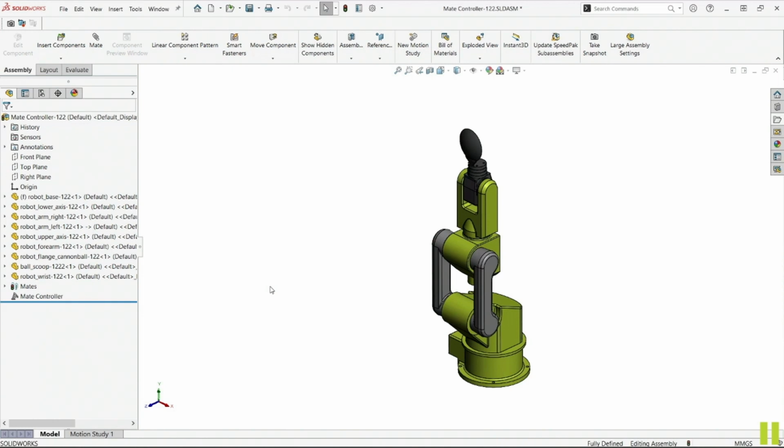Maybe you would have to make those flexible. I'm not 100% sure if that would work, but when you have an assembly and take it into a larger one, it's basically treated as one component. So all those mates within that, it's treating that as just one component. It's not calculating those mates every time, for performance reasons, trying to help with that.